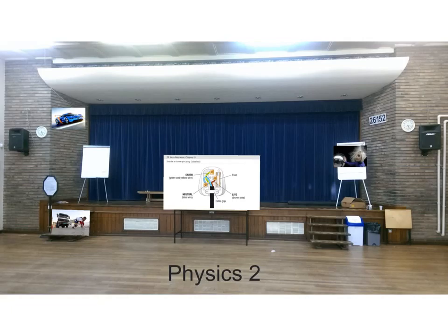Electrical faults are dangerous because they can cause electric shocks and fires. Never touch a mains appliance or plug or socket with wet hands. Never touch a bare wire or a terminal at a potential of more than 30 volts. Check cables, plugs and sockets for damage regularly. Check smoke alarms and infrared sensors regularly. When choosing an electrical appliance, the power and efficiency rating of the appliance need to be considered. Filament bulbs and halogen bulbs are much less efficient than low energy bulbs.